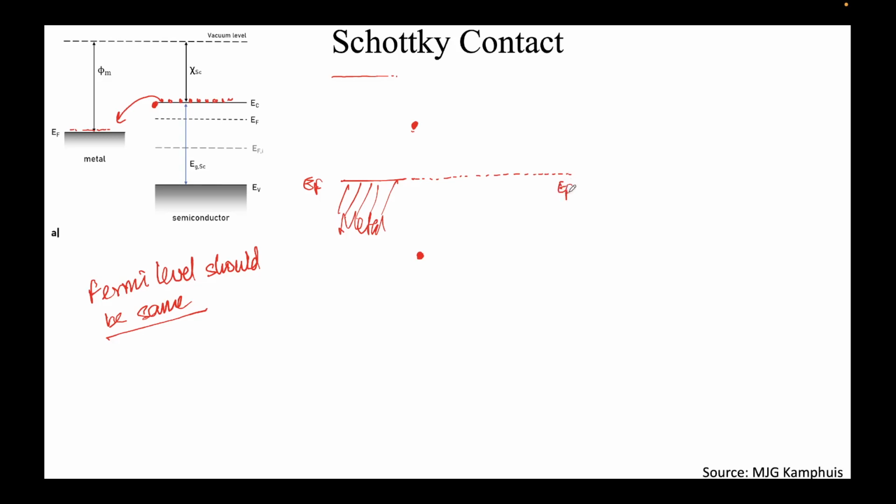We also know that in the bulk, this region is called the bulk, because the junction will have very little effect and will not penetrate deep. Since this is an n-type semiconductor, the conduction band should be close to the Fermi level, something like this.